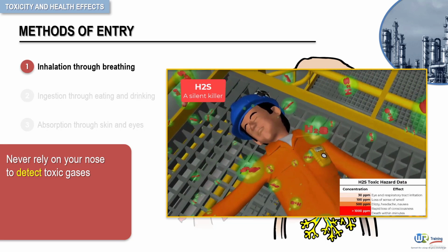It is important to keep in mind here that whenever you work in a toxic or hazardous area, always use a portable personal gas detector and alarm. Install fixed gas detectors and an alarm system in the plant at locations where leaks of hazardous gases are expected. Now, it is best to anticipate the hazards of working with these substances. Always use adequate engineering controls, administrative controls, and wear the appropriate PPE, such as respiratory protection, to avoid inhalation of hazardous gases and dusts. The concept of engineering controls and administrative controls will be discussed in detail further ahead.